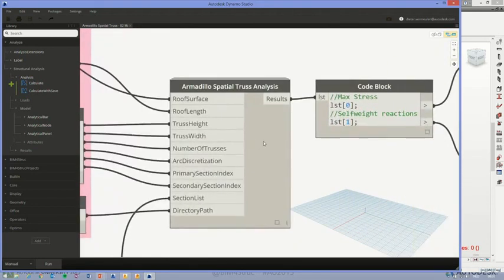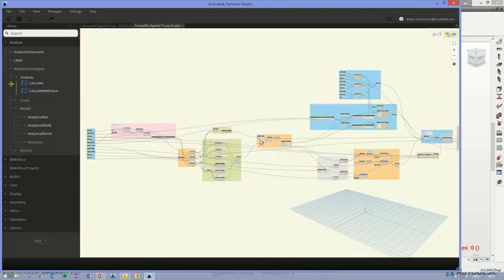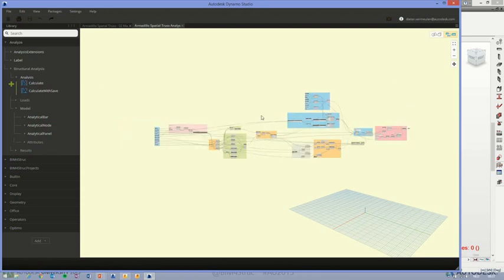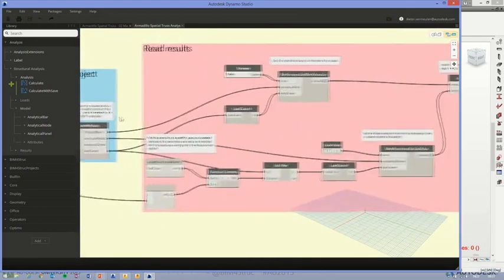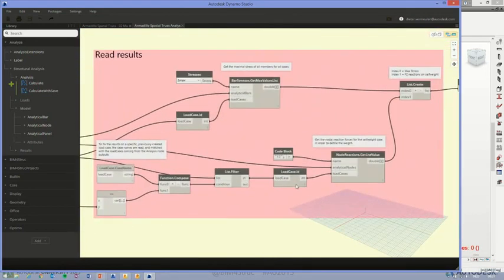Then we have this. These are all the stresses for each load case. So there are 3 load cases, one for self-weight, one for permanent loads, and one for the variable loads. Take these load cases and return to me the values of the stress in that bar. And for the same reason, I want to have the reaction forces of a specific node. So this is 38 kilonewtons. So let's go into the Robot interface, go to the results, the reactions. There it goes. This is this reaction force.